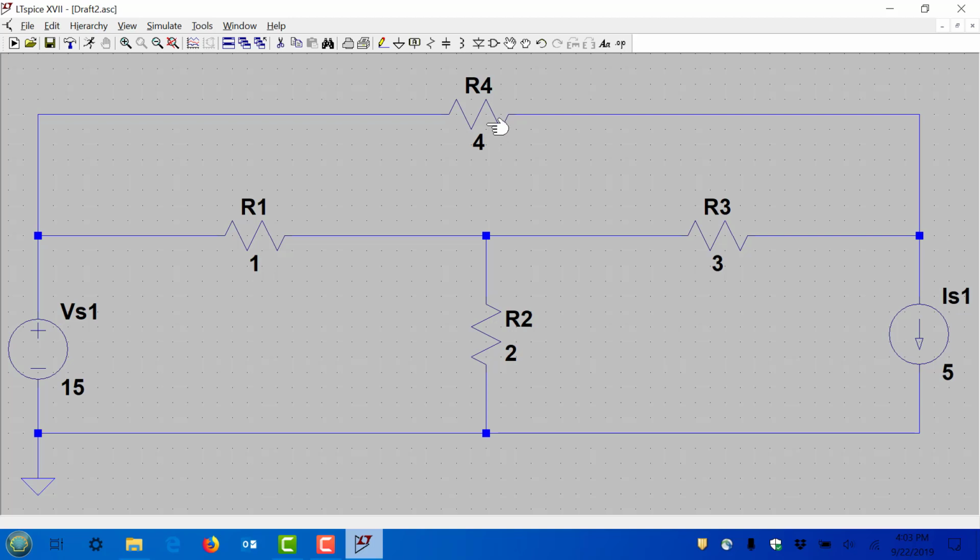Another way is you go to the menu item here, resistor. If you click on that, here you have R5 again, right? You can enter a resistor this way, and then use your Control R, for example, Control R, Control R, Control R, and you can place a resistor this way. Okay, again, right click or escape to get out of that mode.